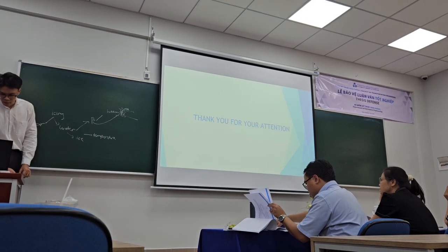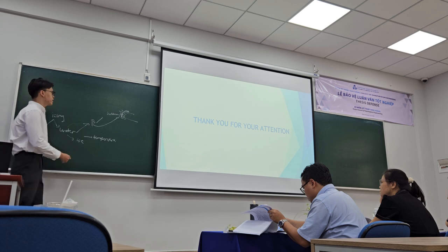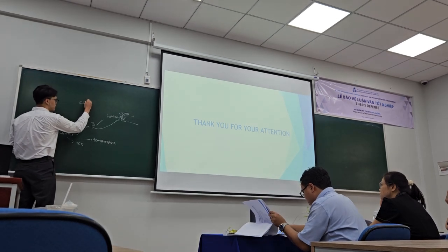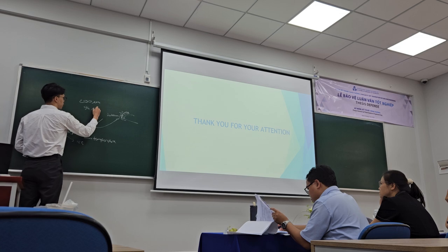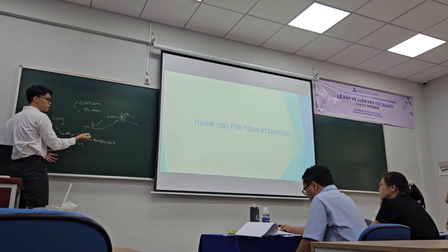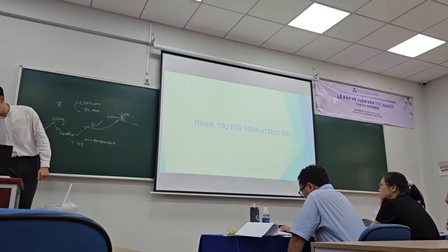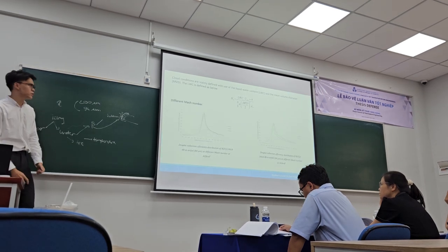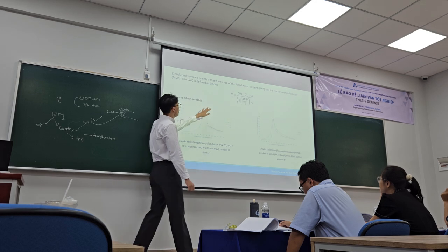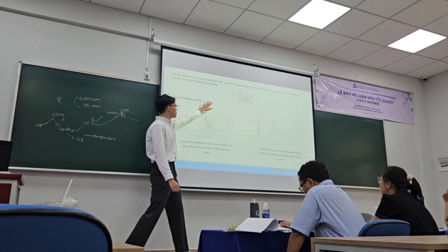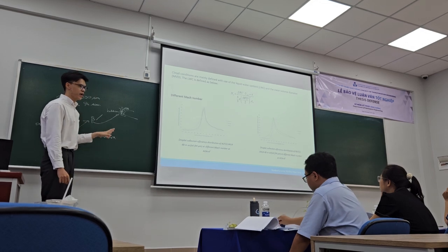So with question number 2: why is the MVD higher, 200 micrometers compared to 94 micrometers, but we don't have a very different collection efficiency? Because we have this formula. As you can see on the screen, this is the formula to calculate the number of droplets in the air phase.